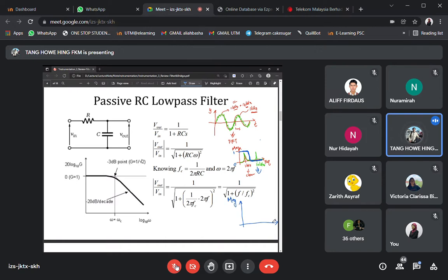Okay, magnitude and then the frequency. So now we are going to get a new spectral plot, which is something like this. The green spectral plot is what we get when we multiply with the window, the blue window of 1 and 0. Therefore, you are seeing that we preserve the 1 kilohertz, but at the same time, we get rid of the 10 kilohertz. Okay. So that is in the frequency domain.